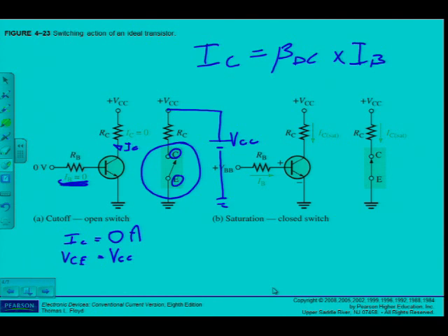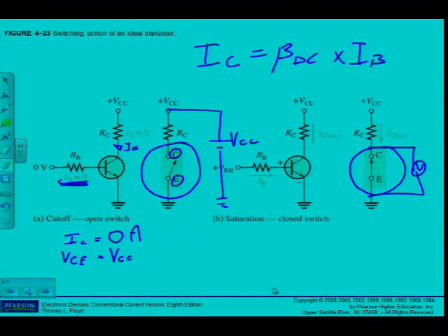On the other hand, at the closed switch, the transistor is in saturation. I can see here that the switch is now closed. If I go and measure over there with a voltmeter, I should ideally measure 0 volts, but it's not an ideal device. We've also mentioned that for a transistor, especially used in this book, we assume it to be approximately 0.2 volts. And the current that flows through this device will now be the maximum current, called IC sat.